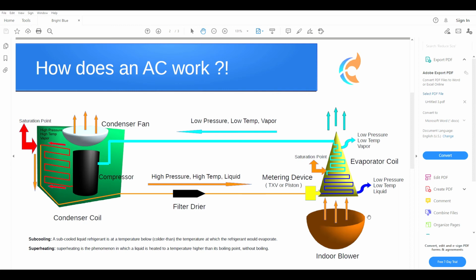And some of the models, Carrier, Goodman, the GMVC ones, are 1590 P6. They have dip switches. Lennox is different, Trane is different. So you have to go through the manual. If you do a bunch of them, you will learn pretty quickly. So yeah, always make sure your airflow is set properly. Try. I know it's hard. I know it's time consuming, guys. But if you have the right tools, it's just going to take you a few minutes.